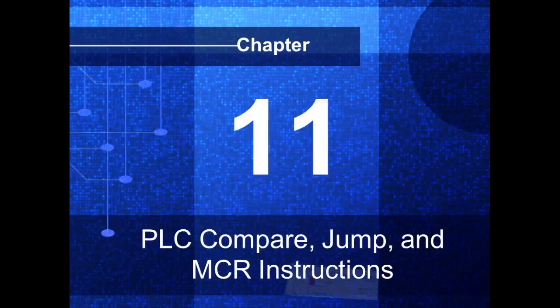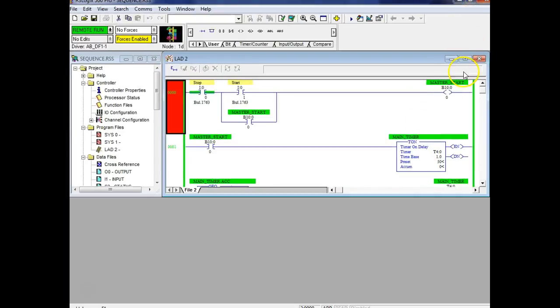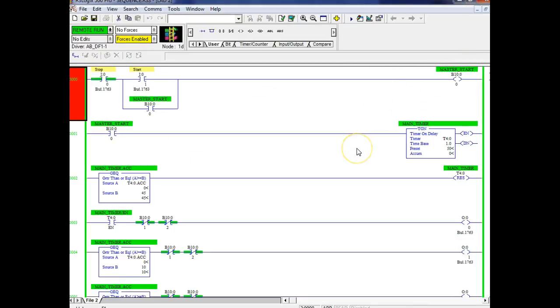What are the requirements for the lab? You have to have a master start stop. Some of y'all actually used your first contacts as your master, and that's not the way it's supposed to work. We're supposed to have another master start stop. They call it a master switch. And the master switch is supposed to enable everything else, right? Some of y'all used the master switch as your first mode.